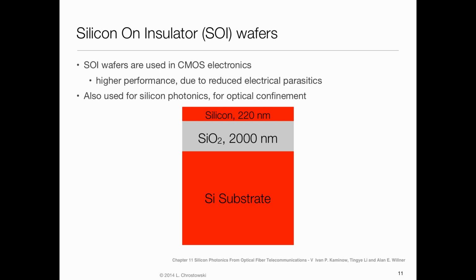It is on top of the crystalline silicon layer that waveguides and devices are defined. Hence, the material properties of this silicon are important for designing optical devices. The examples presented are based on a top silicon thickness of 220 nanometers, which has been used since before 2003.